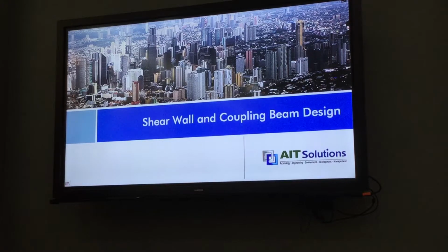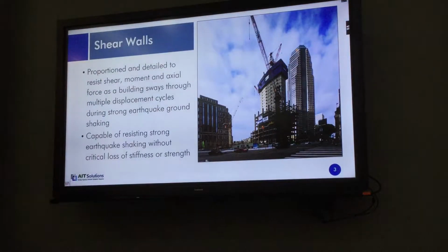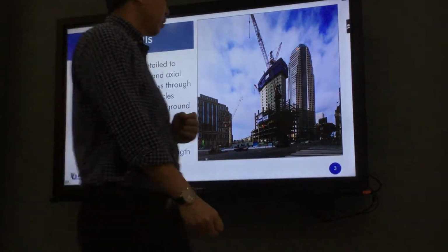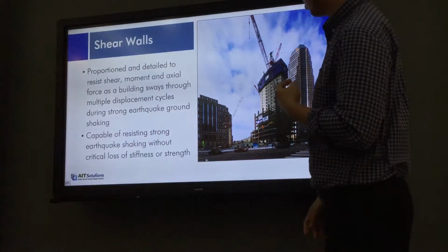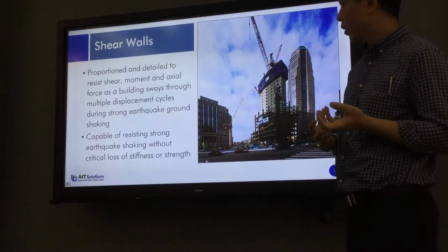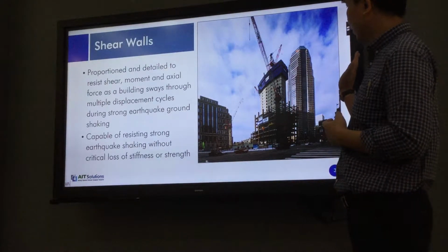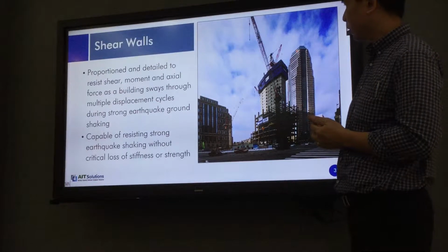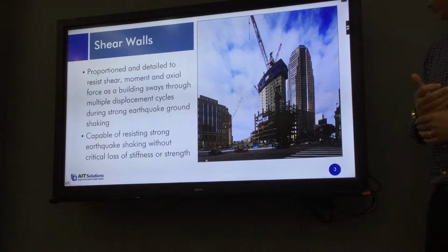I will continue the shear wall and coupling beam design. In tall buildings, we use the shear walls to resist the shear, moment and axial forces to prevent the side sway of the building, especially under the strong earthquakes and winds.